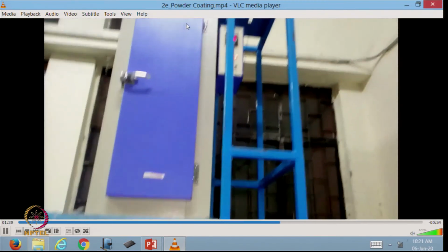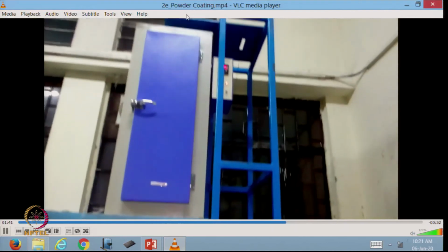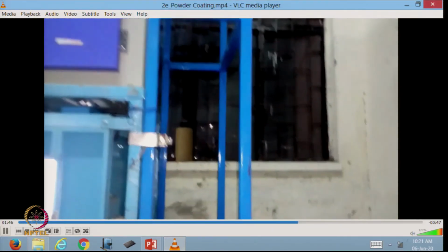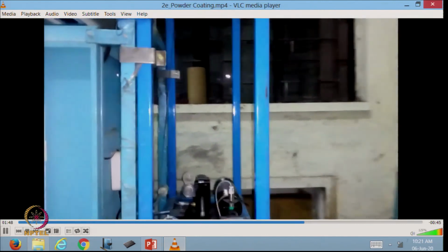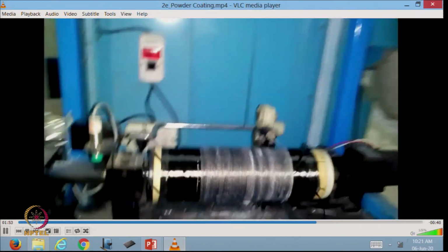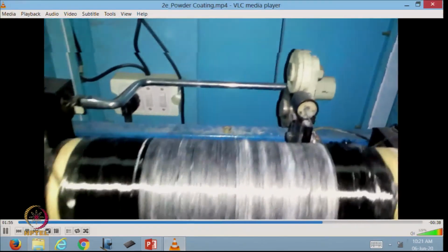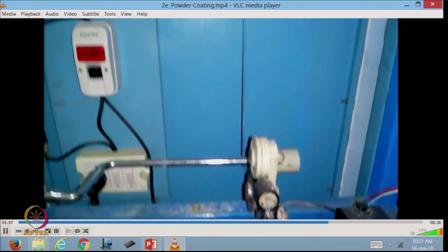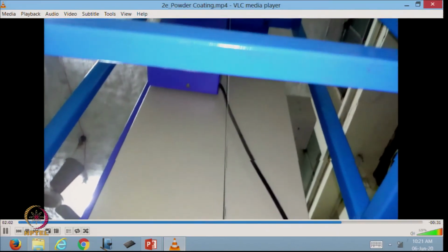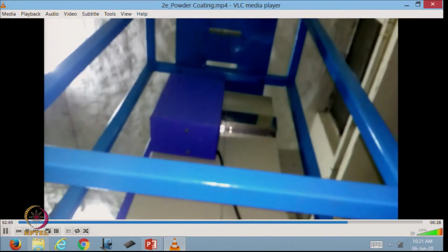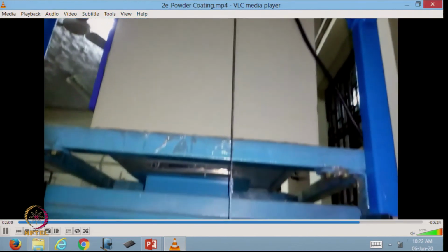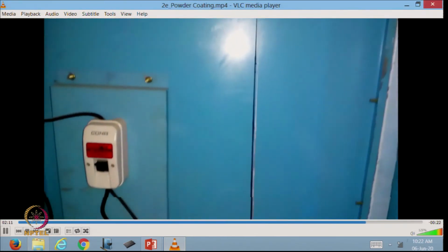And after cooling, here there is a cooling zone, then the carbon tow preg, that is the carbon filament covered with the matrix, here the matrix is polypropylene, is wound on a package. Finally, this will be used for making composite.